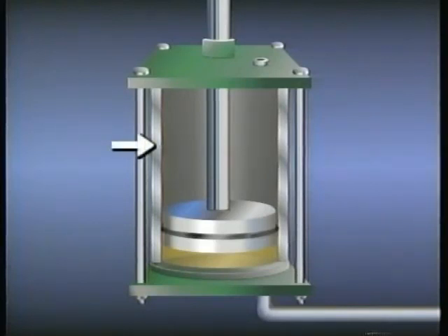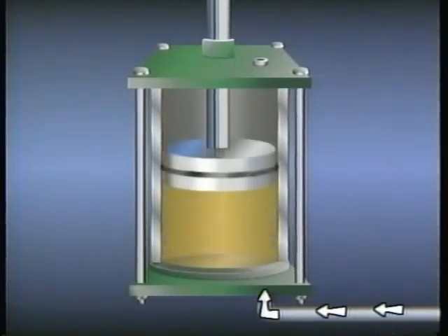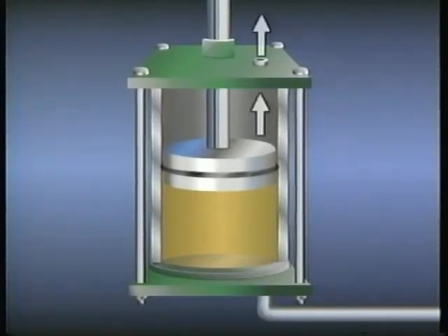The cylinder is a hollow, rigid metal tube through which the piston moves. The fluid port is an opening in the cylinder that allows fluid to enter and exit. The piston ring forms a seal that prevents fluid from leaking between the piston and the cylinder wall. When the pressure of the fluid is greater than the force of the load, it flows into the port and moves the piston upward. This, in turn, moves a device or load that's normally attached to the end of the piston rod. The area on the other side of the piston is vented to atmosphere to prevent air from being trapped and compressed, which could restrict the movement of the actuator.